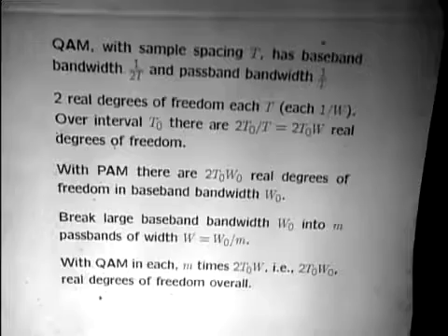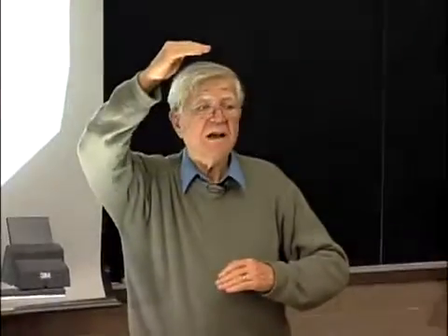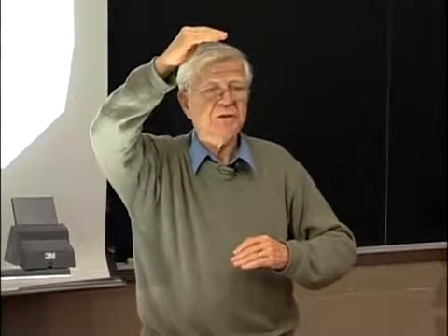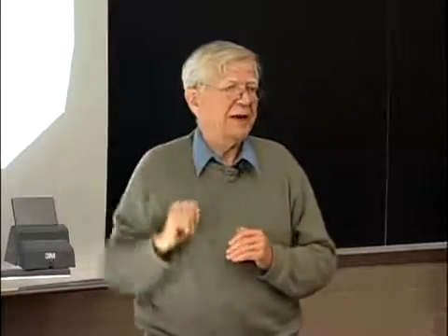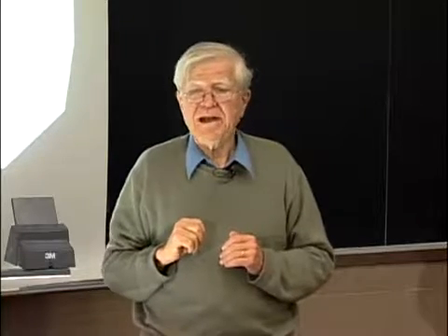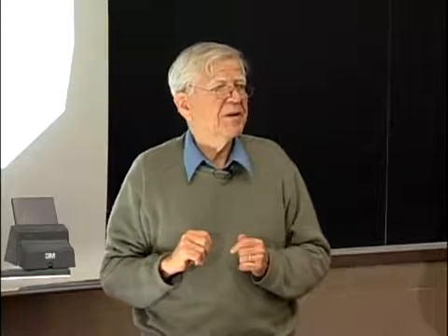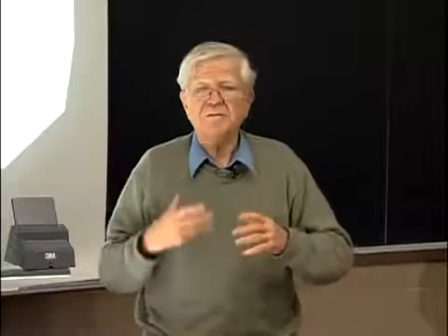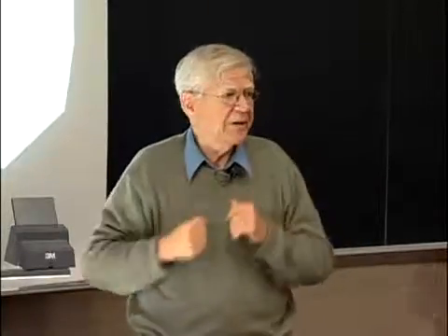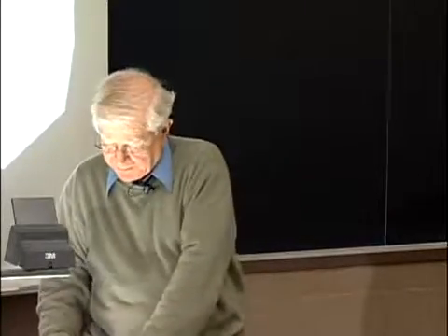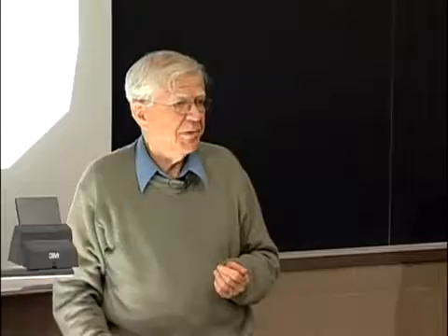Okay, now the thing we want to do is to take this humongous bandwidth and to say, what happens if instead of using this wide bandwidth system, we use a lot of little narrow bands? So we make narrow bands, send QAM in the narrow bands, where in fact we're packing signals into the real part and the imaginary part, which is what we decided we ought to do. And how do these 2 systems compare?